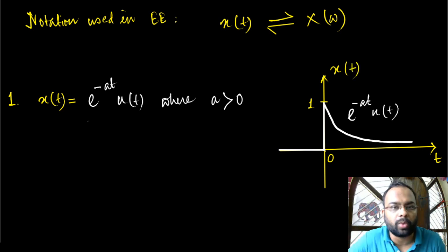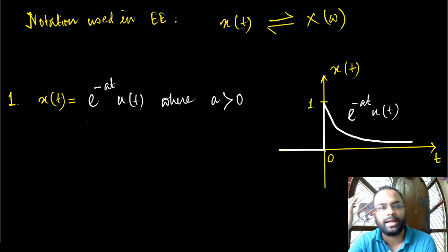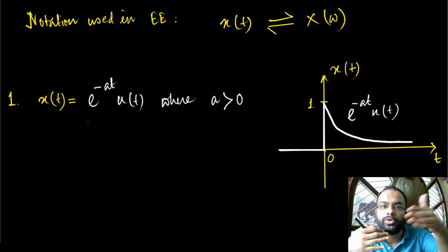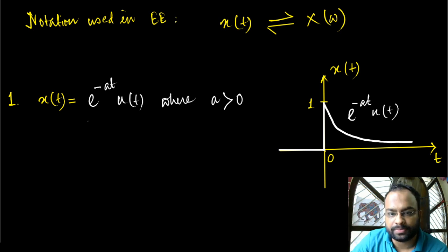We are trying to figure out what frequency components it has. Again, it does not have any fundamental frequency, because the idea of fundamental frequency was obliterated in the last discussion where we discussed aperiodic signals. This is an aperiodic signal. So instead of having discrete frequencies, it would have a whole spectrum of frequencies. It won't have discrete sinusoidal components that you can individually segregate, but it would have a continuous plethora of sinusoidal components.